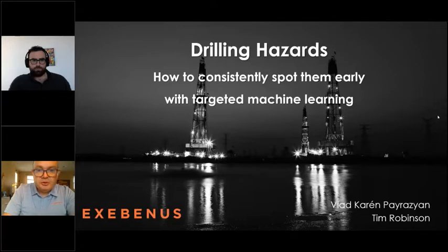So detecting those early, but also identifying its nature. Not only, hey, there is some kind of risk, which is kind of meaningless because you really don't know what it is related to. But if you know that it's related to, let's say, a hole cleaning issue, or to wellbore stability, or to some tight spots in your areas, then you know much better what to do.